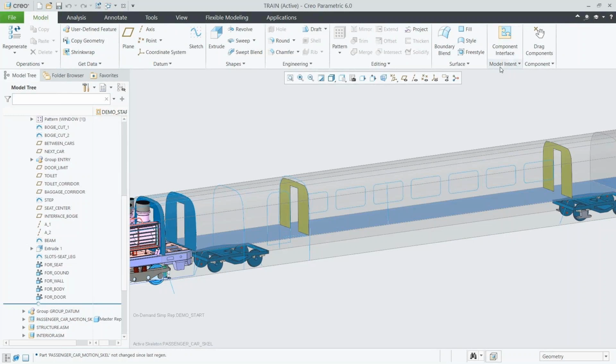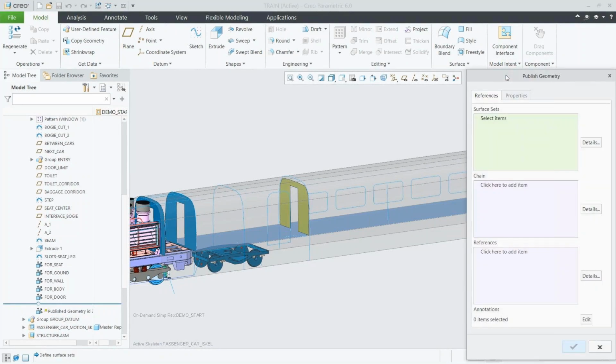So the way that we do this is we take the skeleton model geometry, and we actually copy and share it into the subassemblies that need it. And so in this way, I mentioned earlier, we talked about representation, right? Don't overwhelm yourself. So if this is all from the top level, you won't have to have this top level assembly open in order to work, to reference the geometry from it in the subassemblies, right? So we will also see how this looks in a minute.